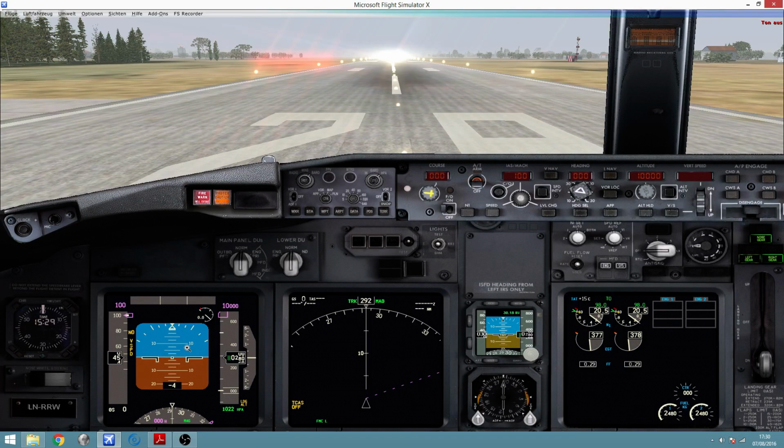So we'll now prepare the aircraft for departure, and the statement says that we have to comply with the before takeoff checklist procedure. The before takeoff checklist procedure is table number 3, and it says QNH set 1022, it's fine. Flight director on, there we go. Auto throttle on, there we have. Indicated airspeed, max selector, and 165 knots, so I will select 165 knots here.